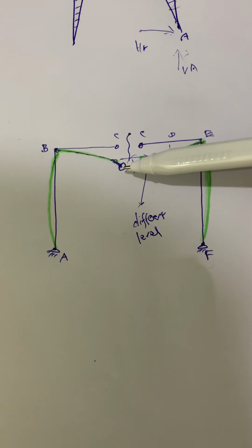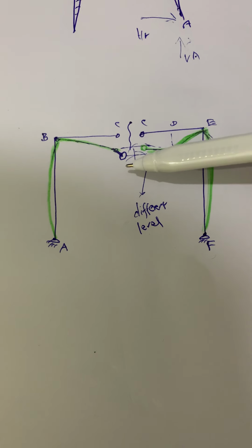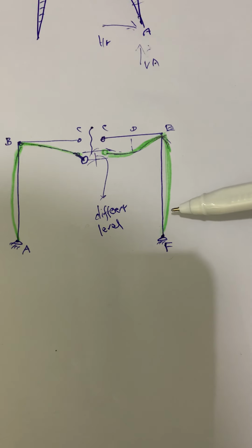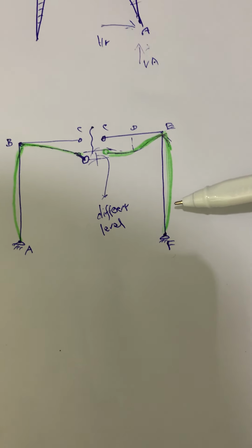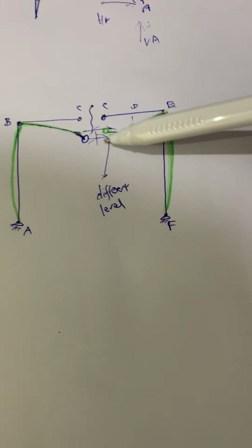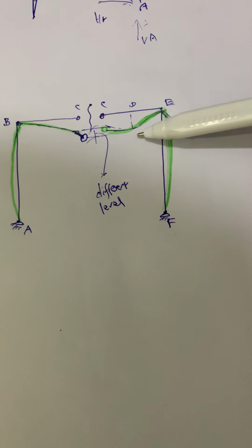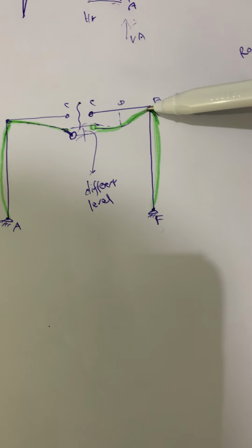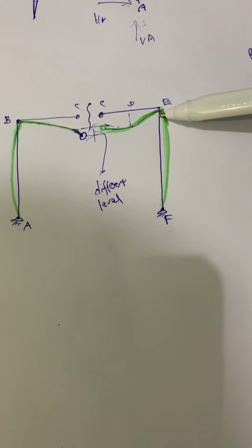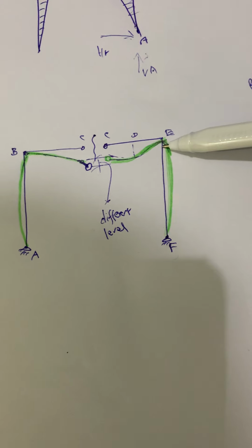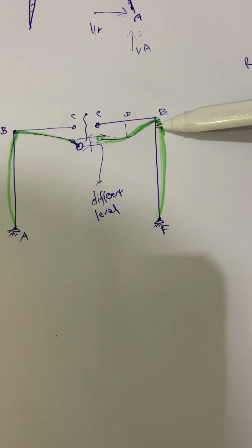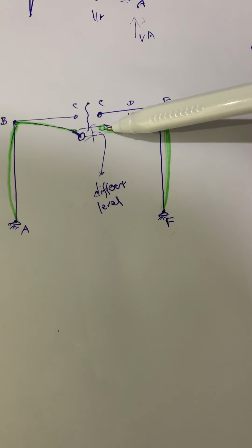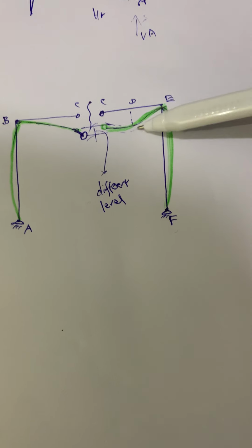We can expect that part of the frame to deflect, as we have seen on the left hand side of the diagram. On the right hand side C, D, E, F, there is an equal bending on the vertical member. This vertical member is equally bending, but at the load W it starts changing the tension rapidly, and then it goes to E, and changes rapidly because it's a rigid joint. On the right hand portion CDEF, there is an equal bending on the vertical member, but the outside tension changes rapidly to inside.